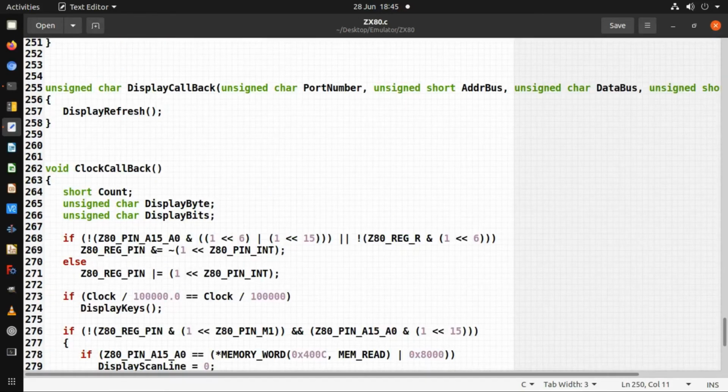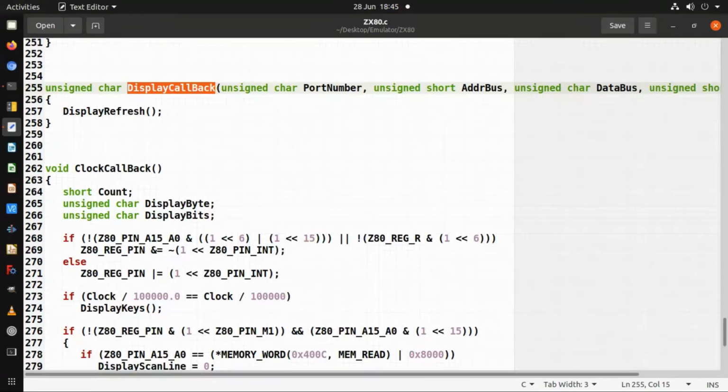And then the display. There's a port which, for every blanking period on the screen, does the work. In the olden days on a CRT display, an electron beam scans down the display, and when it gets to the bottom, it has to move the electron beam back up to the top left corner from the bottom right hand corner, and that takes a little bit of time.